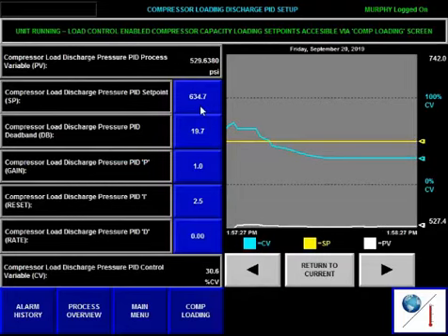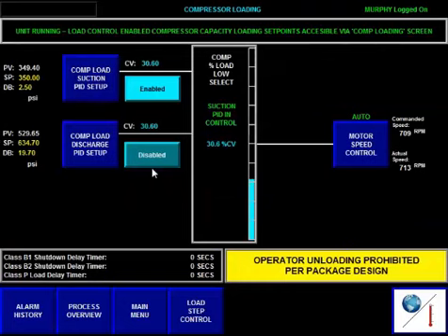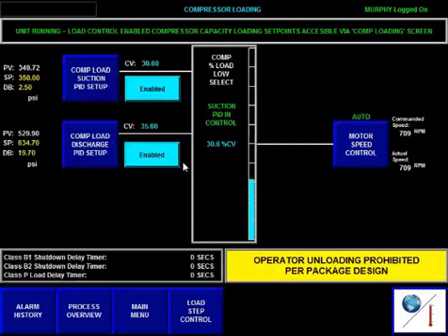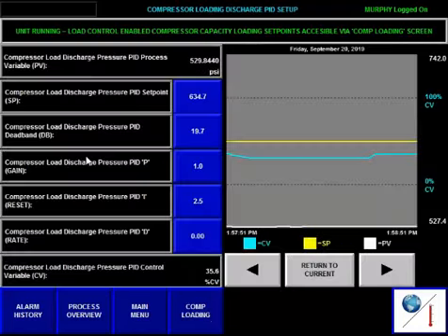The unit may be operated in both suction and discharge mode, and the low selector of the two control variables will be the output to the motor speed. At the moment, the unit is running in suction control. Now turning off discharge.